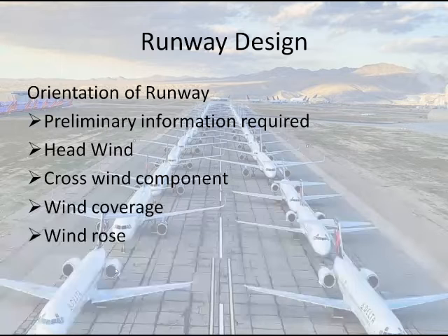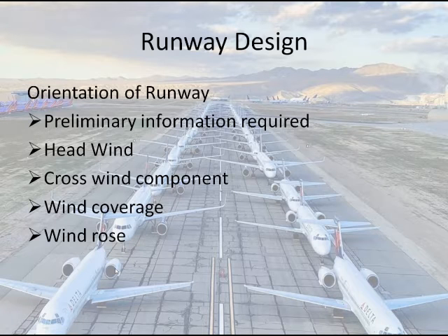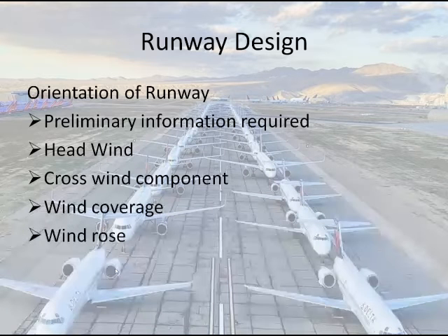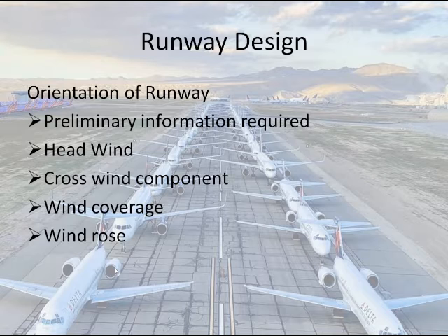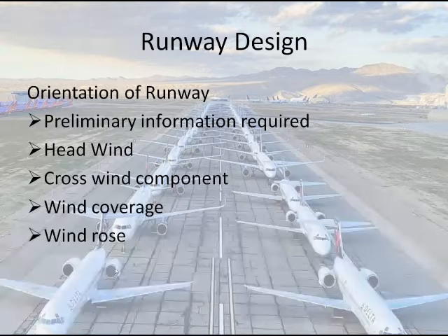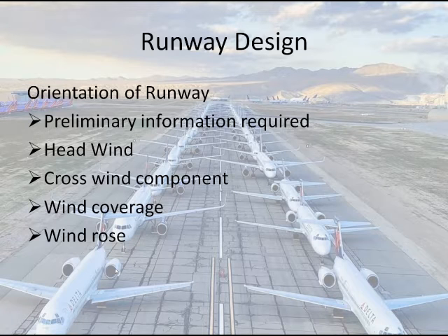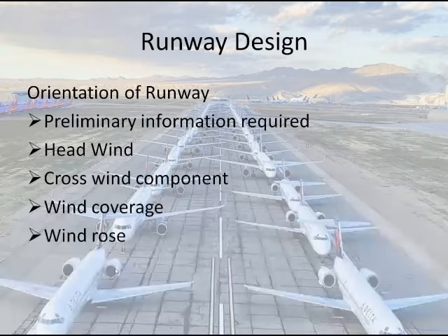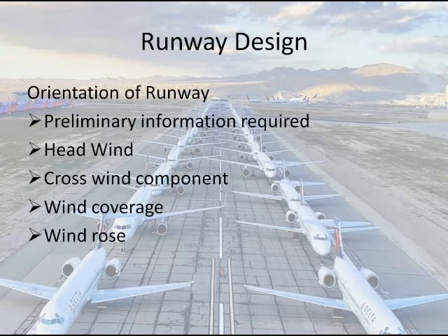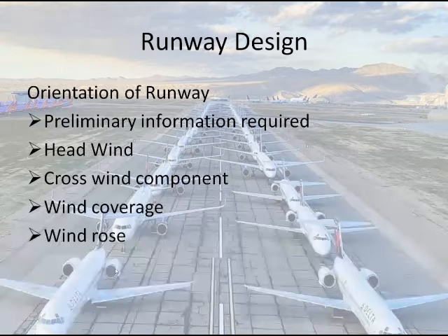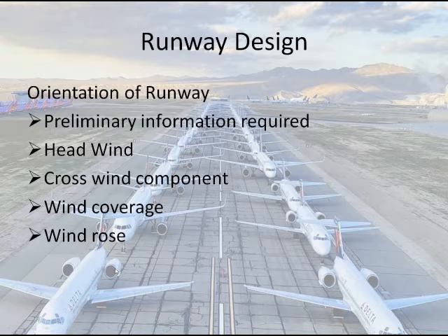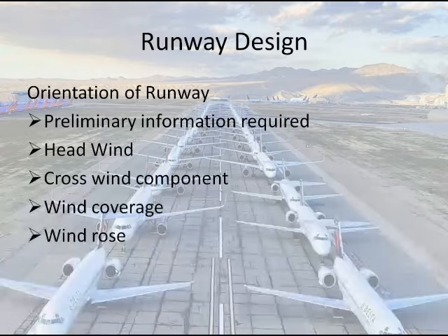In general, the arrangement of runways and the connecting taxiways should comply with the following conditions. First one, to avoid delay in the landing, taxiing and takeoff operations, and to cause the least interference in these operations. The second one is to grant the shortest taxi distance possible from the terminal area to the ends of the runways, to make provision for adequate taxiways so that the landing aircraft can leave the runways as quickly as possible and follow routes as short as possible to the terminal areas.